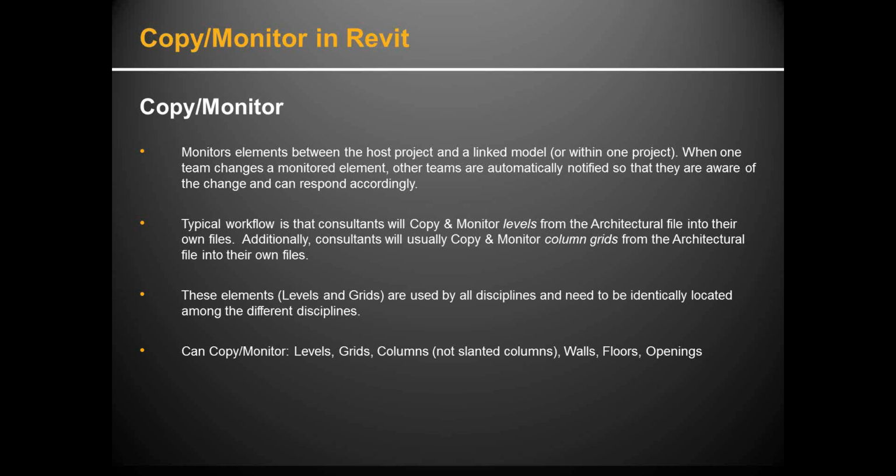Now, the first portion of this webinar will cover the most common use of the Copy Monitor tools, which specifically is when the consultants, basically the engineers usually, will copy and monitor the levels and the grid lines from the architect's Revit model. And then in the second portion of the class, I'll go through some of the processes of copy and monitoring specific fixtures.